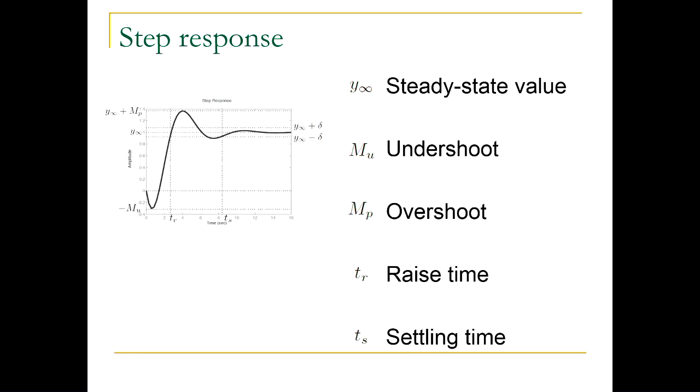So what we will learn is to basically say, all right, here is a transient, and in this particular situation, it makes sense to impose these conditions on rise times, overshoot, etc. And then you would learn how to design this controller to achieve that. Typically, that would be appropriate for the problem at hand. Okay, that's how we use these sorts of transients in design.